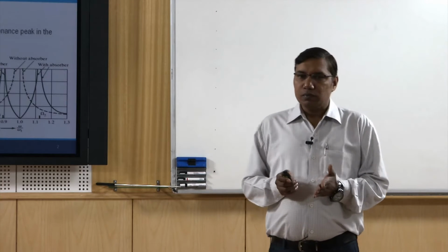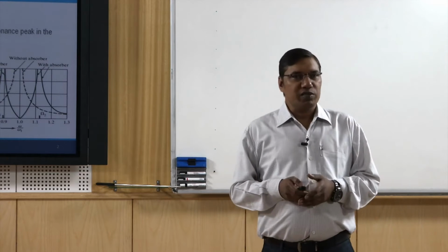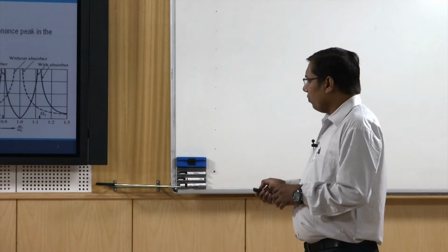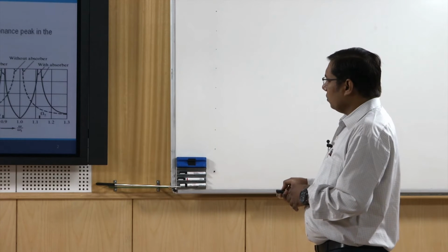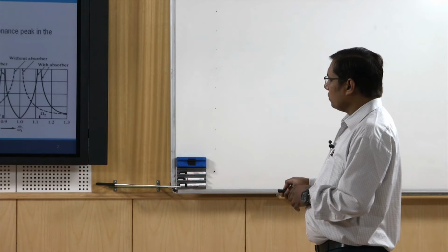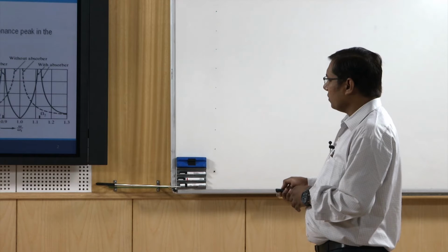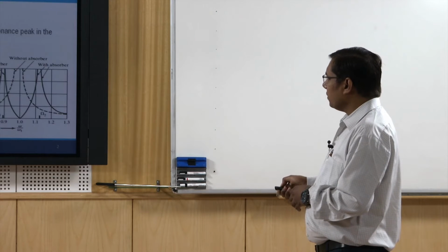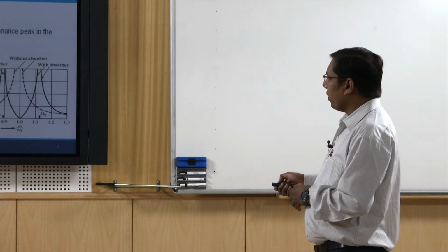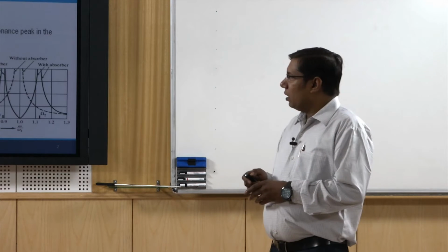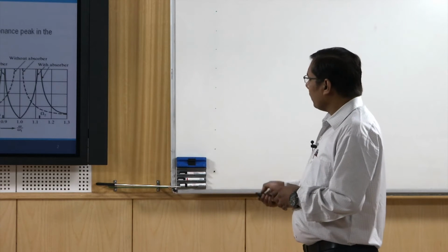Therefore, if it passes through the lower resonant frequency of the system, for example, here if it passes through 0.8, although its operating frequency is here, it has to pass through this frequency. So, at this frequency the amplitudes of vibration are quite high, quite large, and this we can also see from here.